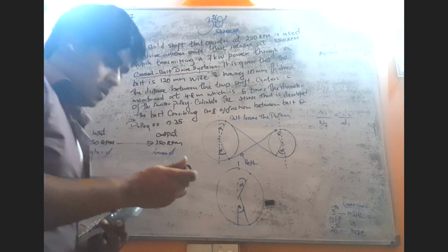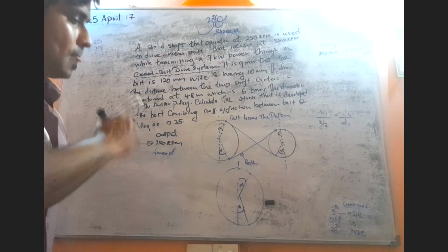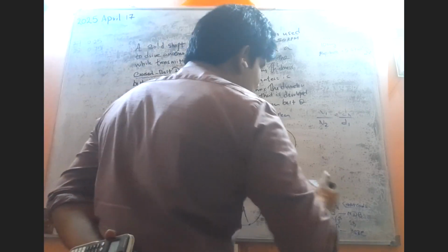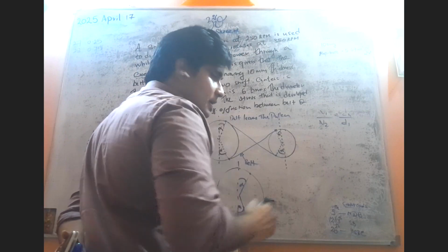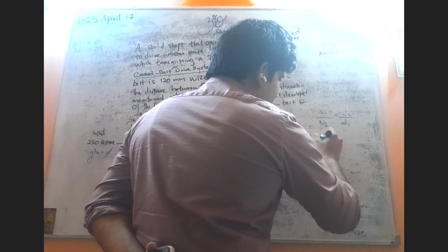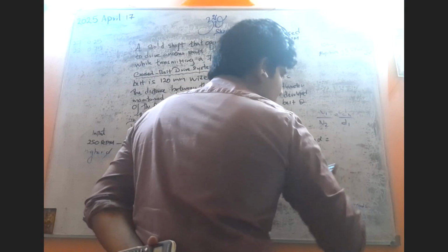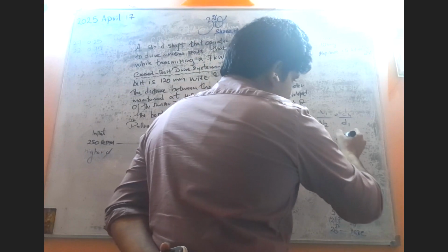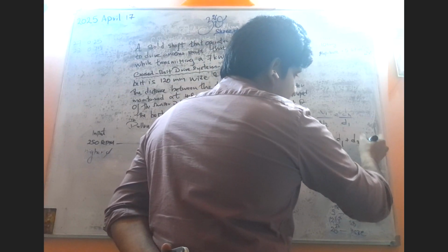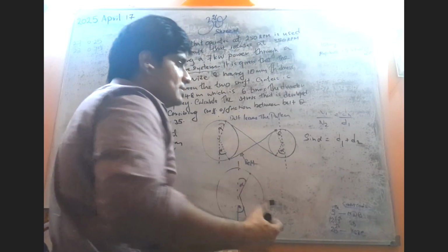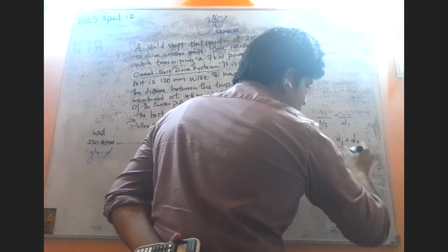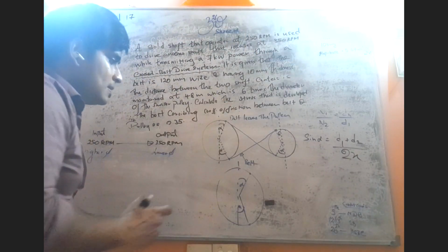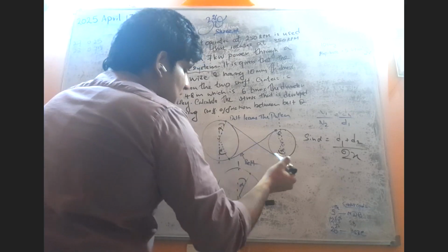Now, there is an equation in order to find this alpha. So I will write it here: sin alpha equals the summation of the pulley diameters, D1 plus D2, divided by 2x. What is this x? x is the distance between the shaft centers.